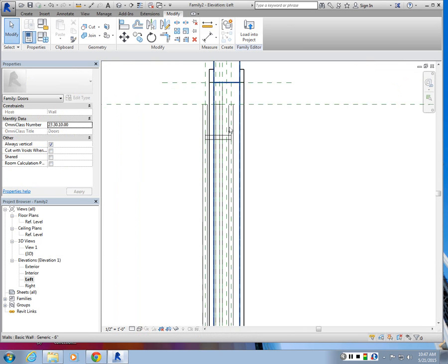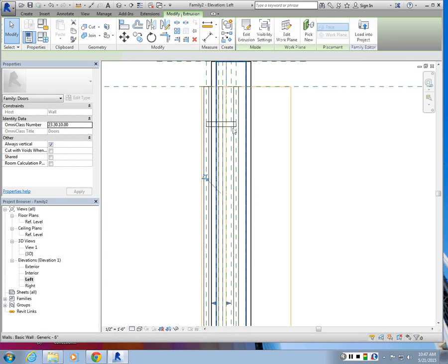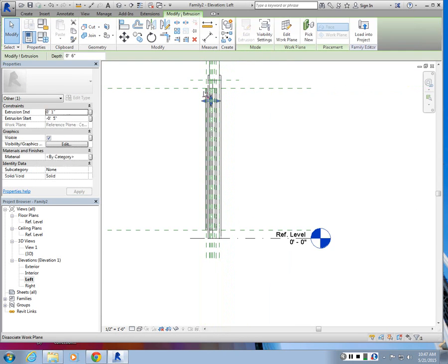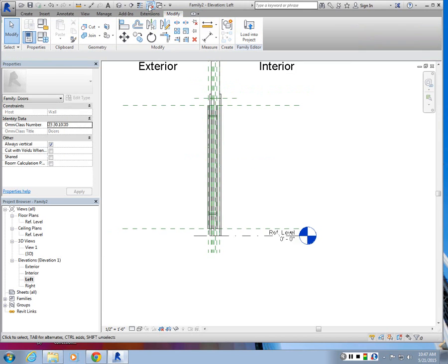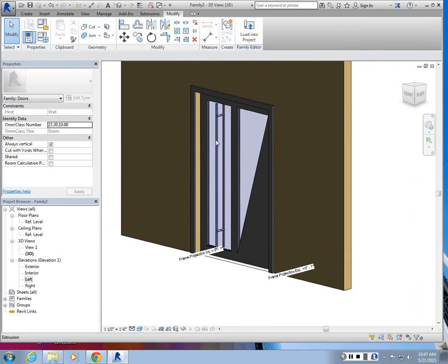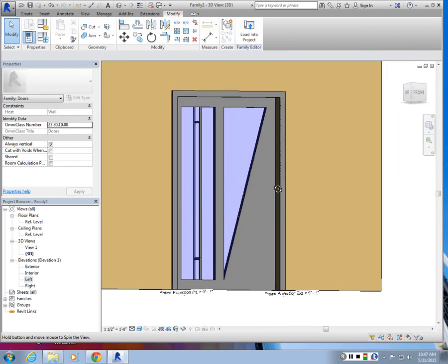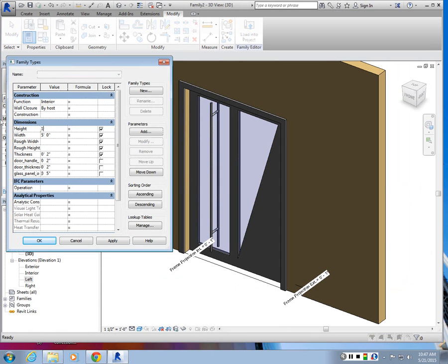The last thing I'm going to do is select this handle, and do draw mirror axis again, and find the midpoint of the door and make a copy of it, so that you get two copies, one on the bottom and one on top. Right, so now I have a door. And do some stretching. Stretch the heights.